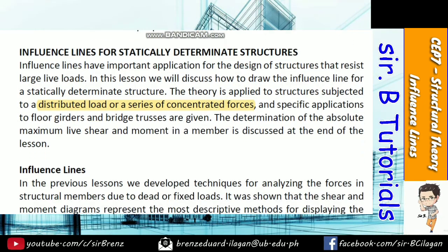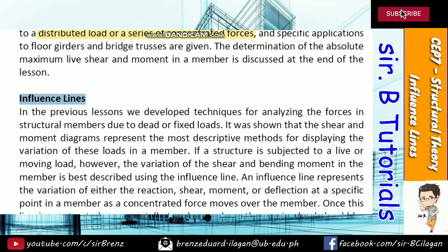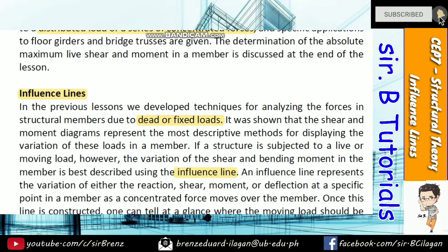Okay. Influence lines. In the previous lessons, we developed techniques for analyzing the forces in structural members due to dead or fixed loads. So yung mga naunang part, this is all about the dead or the fixed load. It is shown that the shear and moment diagrams represent the most descriptive methods for displaying the variation of these loads in a member. If a structure is subjected to a live or moving load, however, the variation of the shear and bending moment in the member is best described using the influence line. So kapag moving load na, when it comes to shear and bending moment, the best method of describing a member is using the influence line.